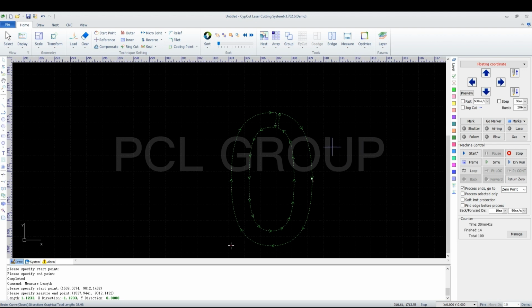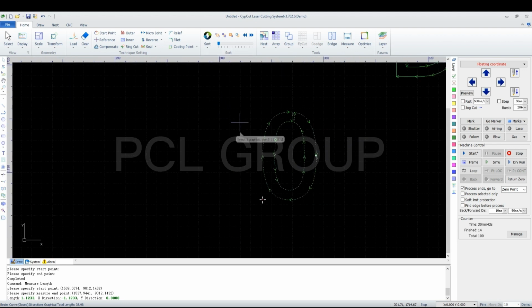Now let's come to the last feature. If we don't want parts get automatically optimized when input, click Manually Optimize. In the drop-down menu, we have this break grid, which is used to cut up the inner waste so as to avoid it going up and getting in the way of the cutting head.